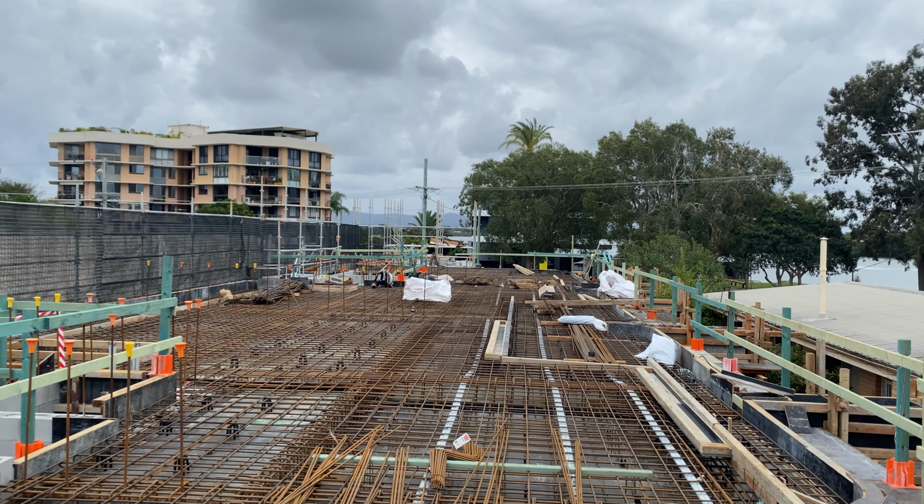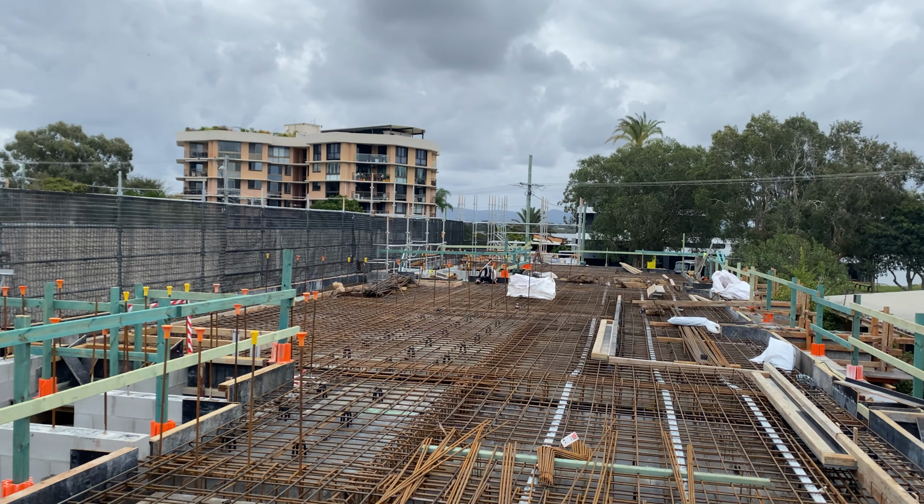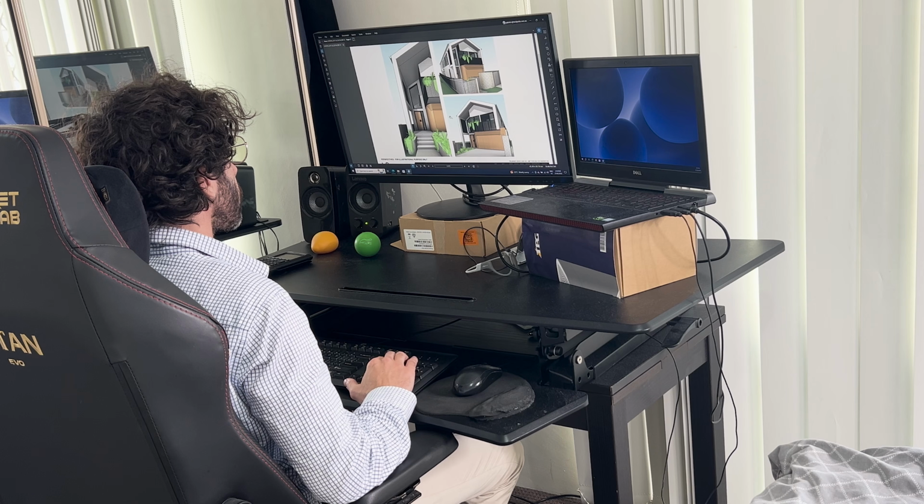So how do you choose the right one? Assuming you've got the budget to invest, I think it comes down to four things. Number one, your needs. First, think about the types of projects you usually work on. If you're doing lots of post-tension slabs and reinforced concrete buildings, then RAM, Inductor, or ETABS are probably your go-to. But if you're mainly handling smaller residential and commercial projects, a general purpose software might be all you need. Most engineering offices will have at least one general purpose and one specialized software.